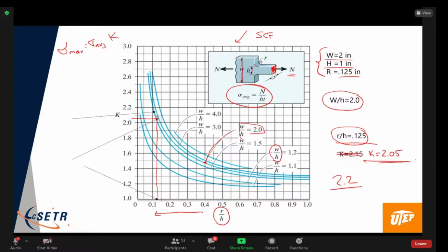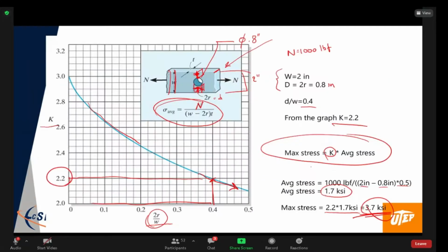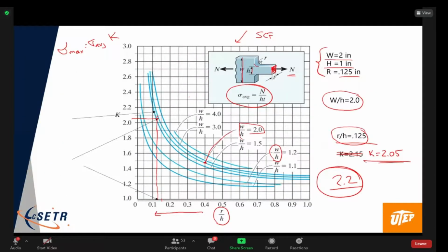So around each rivet hole, you had a significant stress concentration factor, kind of looking a lot like what is going on here. So they had cracks originate at the rivet holes. And if you've seen that, the rivet lines are pretty lined up. So the crack just propagated across all the rivet holes and eventually fractured the ship right in half, which is why now you tend to see ships are not riveted. They're welded together, okay?